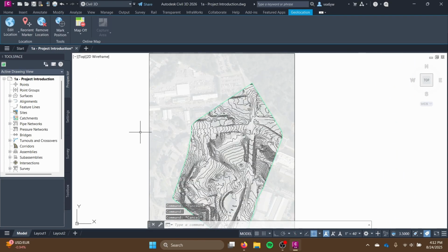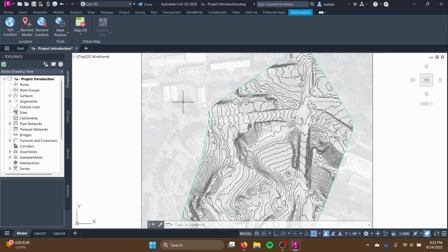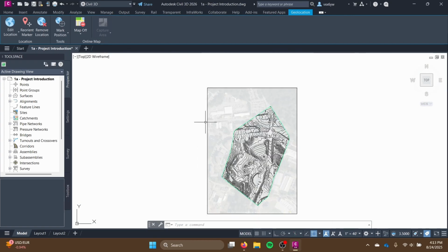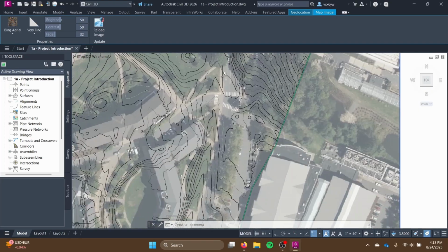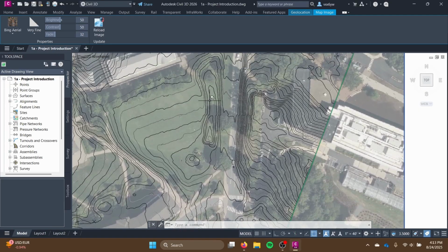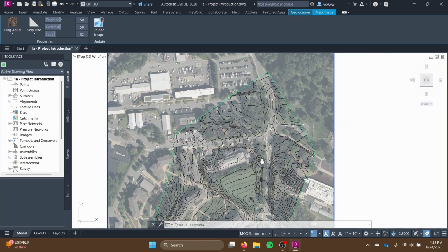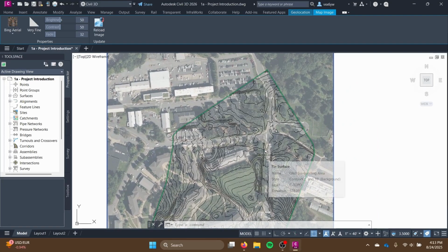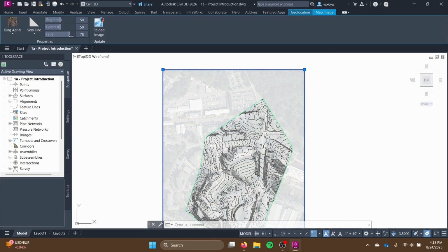One thing I want to make a note of right now, and I'll remind you this again in the future, the data that you survey and the satellite imagery will not line up perfectly. So for example, even just this satellite imagery and the satellite data, you can see here that there's very clearly kind of a road here, but in the imagery, the road is over here. So you can see there's this offset between here and here where we think the road should be. So the imagery is a great guide for you, but it should not be how you reference or make your absolute final design. So I recommend keeping the fade fairly high. Use it to orient yourself, but don't use it to make your full design.